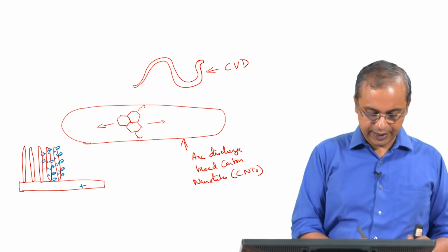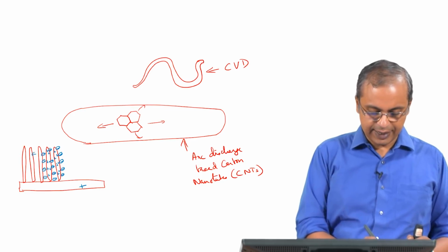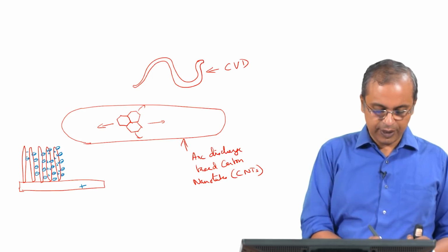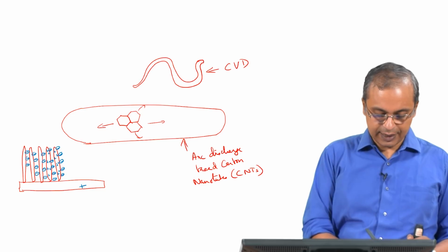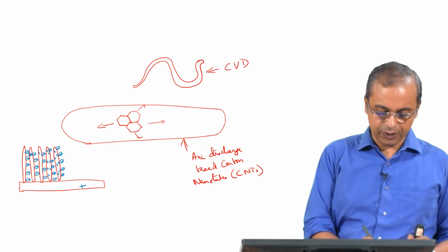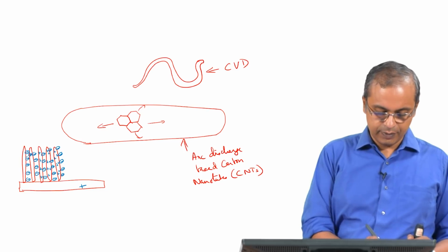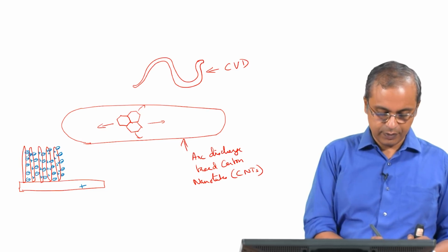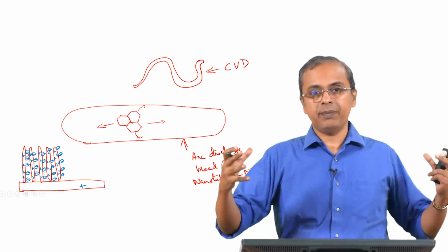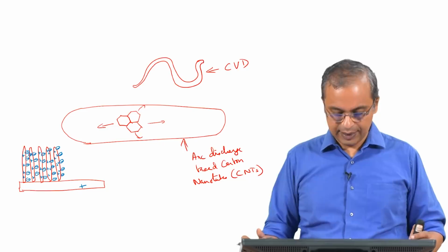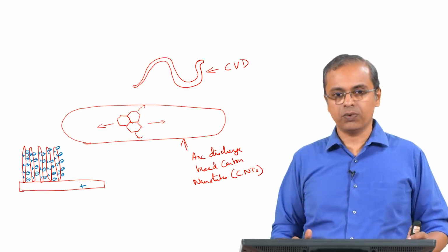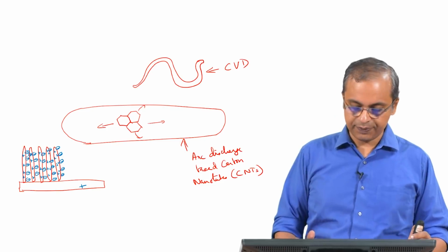So, you get all this negatively charged ions which are collecting in the gaps between these carbon nanotubes, because you have the charge that has been built on the carbon nanotube and the positive charge is sitting in the carbon nanotube. So, this way you now have a very 3-dimensional structure over which you have a lot of charge that has been held together. Okay. So, this is how you take a flat structure and generate a lot more charge and store it in this structure.